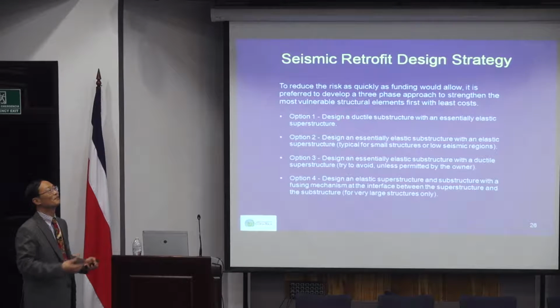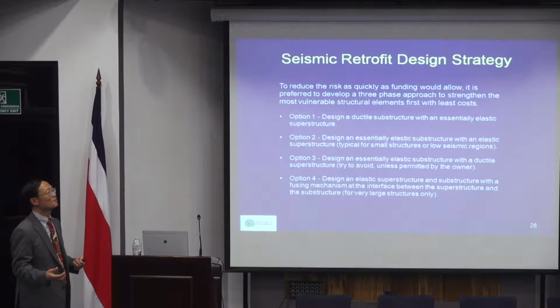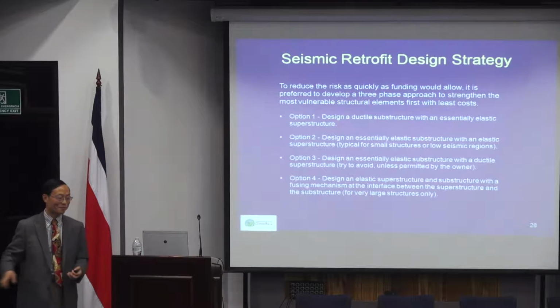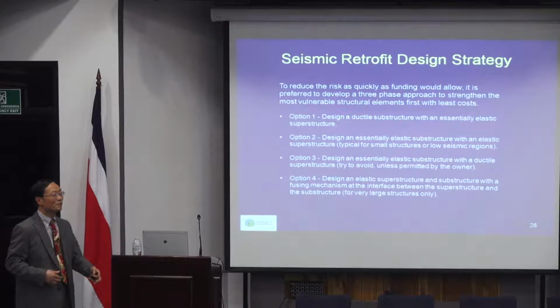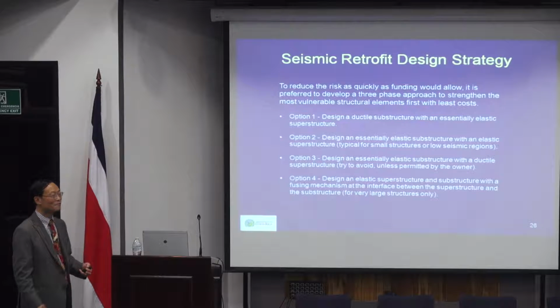For example, if you find drainage issues, you may say, okay, maybe we should try to eliminate deck drainage as much as we can. We don't need that many. We can do a more detailed calculation. Once you have less drainage, you have fewer things to maintain.